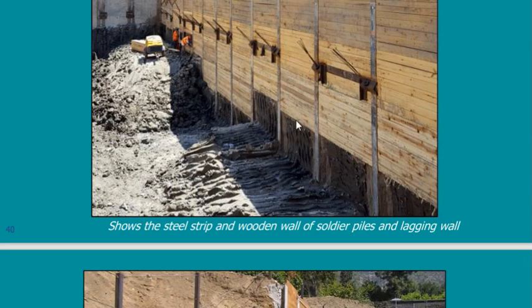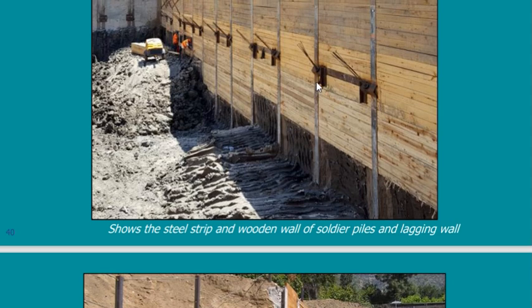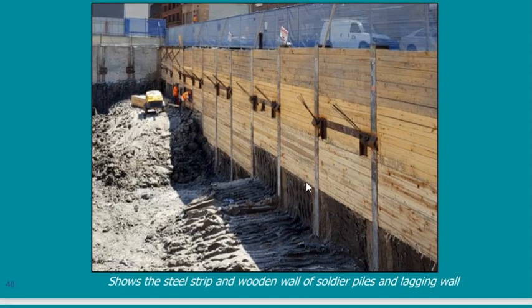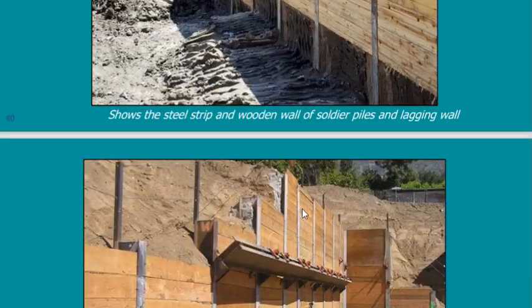strong to the extent that we did not need to push the wooden lagging below, because it will stay in place. So the wooden lagging was used from this height to this height because there was soil, but maybe at this location it was rock. I don't need wooden lagging, so they did not push the wooden lagging further below.